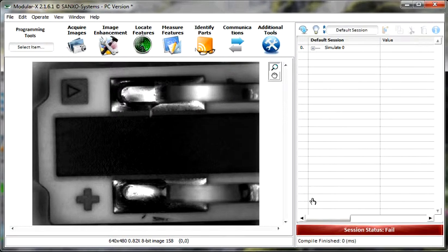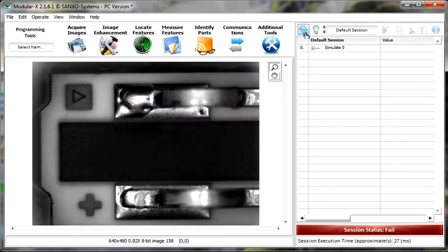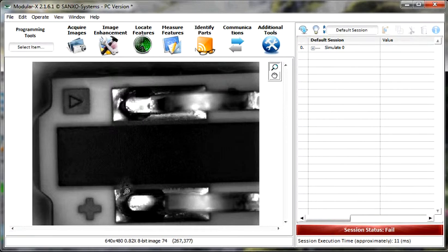This connector has two soldering points here and the resistive material in the middle. We have to check the quality of the soldering, if there is enough solder, and look for burns and contamination around the pins. For example, this is a contamination, and also let's look for some burns on the image like this one here. You can download these pictures, so if you want you can follow the instructions of this video.